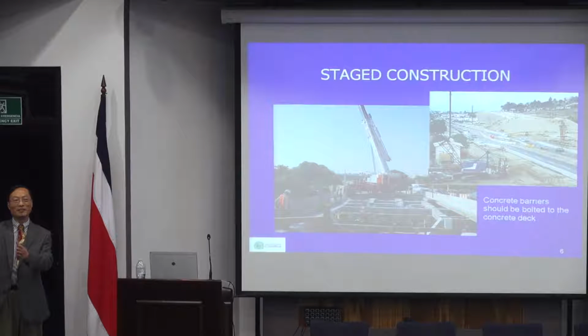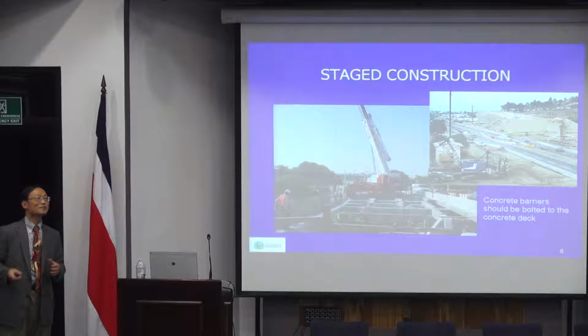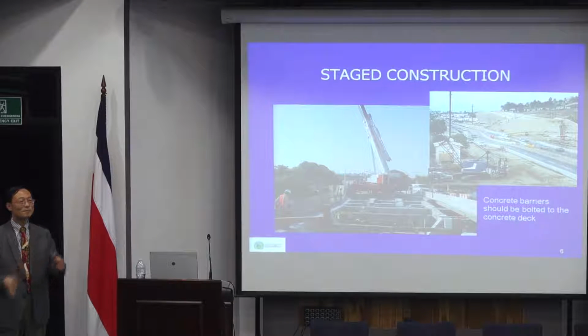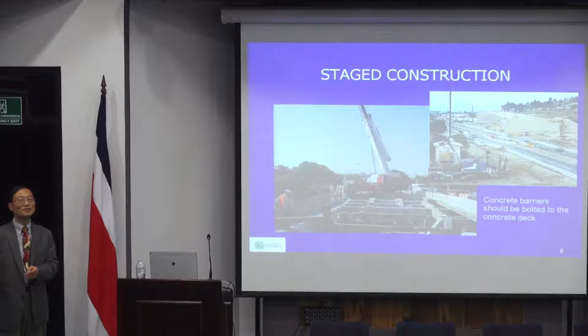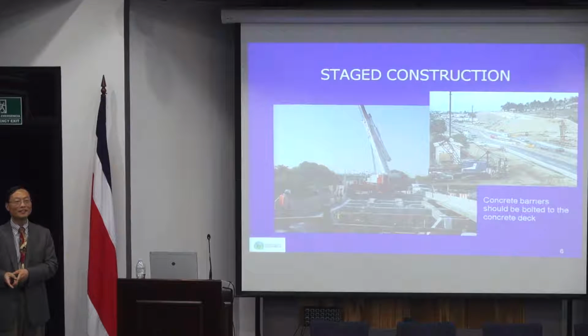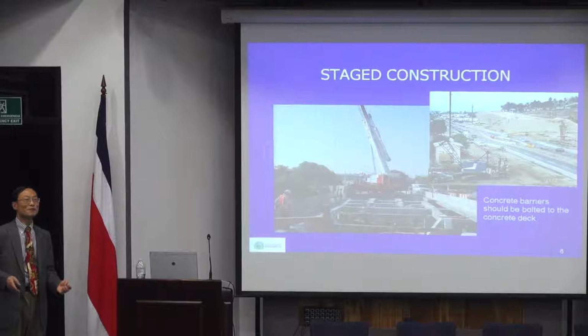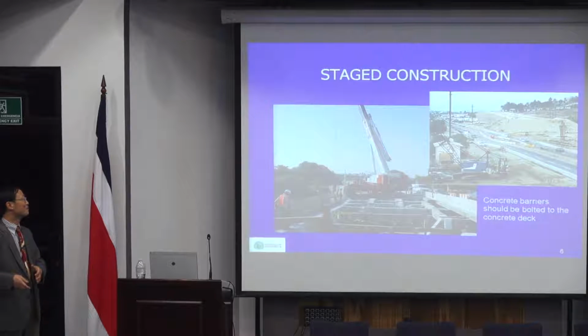They may say, we need to keep 1 lane or 2 lanes during construction. Ideally, you should keep 2 lanes, so people can travel in that direction. If you only keep 1 lane, then you probably need a person to control traffic, and that's only for very rural areas where you don't have much traffic. In heavy traffic areas, that may not be practical, so we have to keep at least 2 lanes.